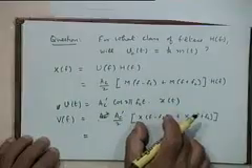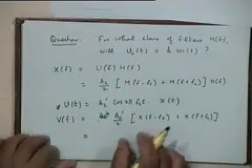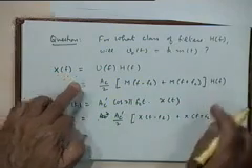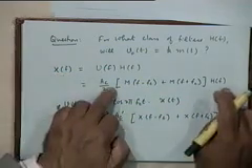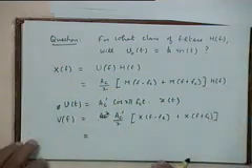How many terms will I get now? Four terms. I'll shift each of these two terms: I'll find X(f minus f_c), I'll get two terms, find X(f plus f_c), you'll get another two terms. You'll get four terms.